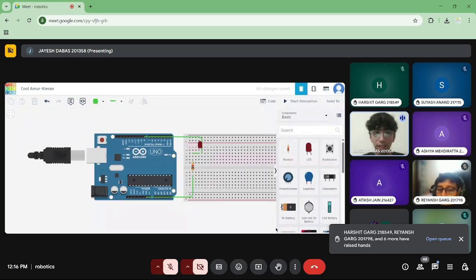So it will turn the power on and off at certain time frames so that it seems like it is running at 50% power, but it's on and off only, right? So it is a way to simulate an analog output using digital pins, as simple as that. When we get into the coding part, we will see that even though we're using a digital pin, we still write analog when we are using a motor.